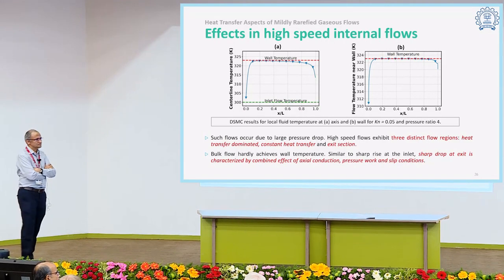Amit, just a quick question. In which dimensionless number do you have heat capacity embedded? For example, if you did this experiment with helium instead of nitrogen, which part of this experiment would capture that change? So you are thinking about the rho Cp term? Yes. Would rho Cp occur anywhere in any one of these dimensionless numbers, or would you anticipate the behavior to be the same for a given Knudsen number, Reynolds number, Peclet number, whether you use helium or nitrogen? Okay, so sensible heat in the gas.